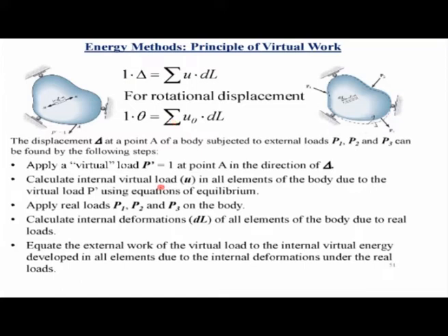Now what is the virtual internal energy? We have already calculated the internal virtual loads due to this unit virtual load in all the elements of the body, and also due to the applied external loads we have calculated the internal deformations of all the elements of the body. So the virtual load times the internal deformations due to the applied load will give you the internal virtual strain energy.